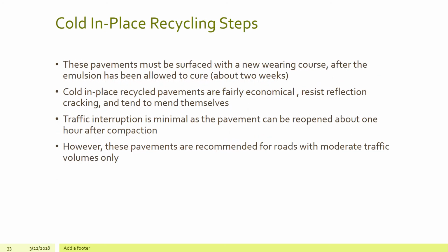These pavements must be surfaced with a new wearing course after the emulsion has been allowed to cure, and we're looking at basically around a 2-week time frame. Cold in place recycled pavements are fairly economical, resist reflection cracking, and tend to mend themselves. Traffic interruption is minimal as the pavement can be reopened within about an hour of compaction. However, these pavements are recommended for roads with moderate traffic volumes only.